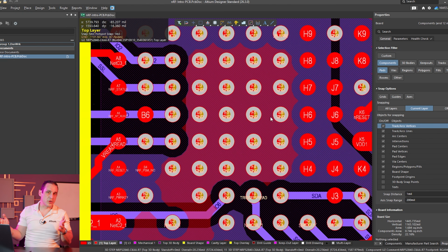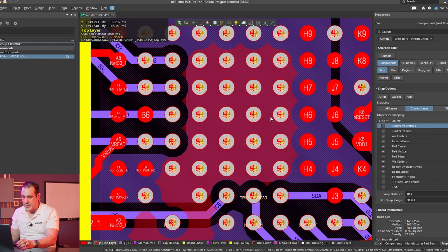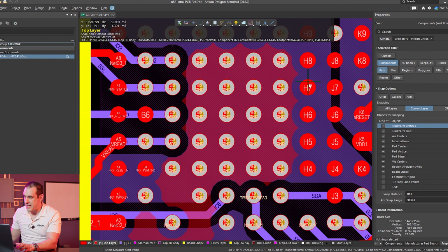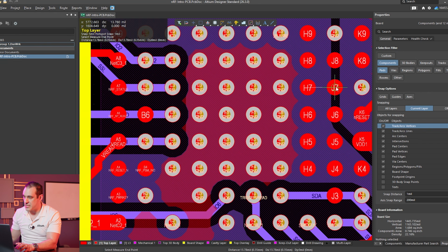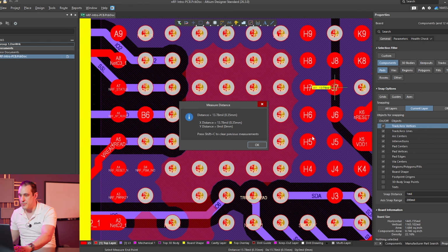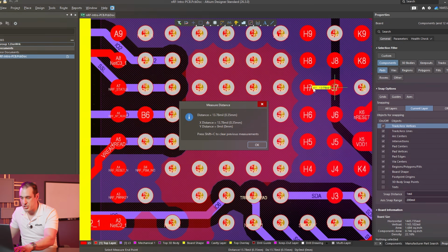Now, one of the things that's really important in these designs is the pitch between the pins in these components. And you can see here, just with a quick measurement of the pitch on this design, it is 0.35 millimeter pitch between the pins on this BGA. Now that number is really important because it's going to determine how large the vias can be. Of course, we're going to run up against the clearances and we'll get that information from the fabrication capabilities, but we need to know how big can the vias be?